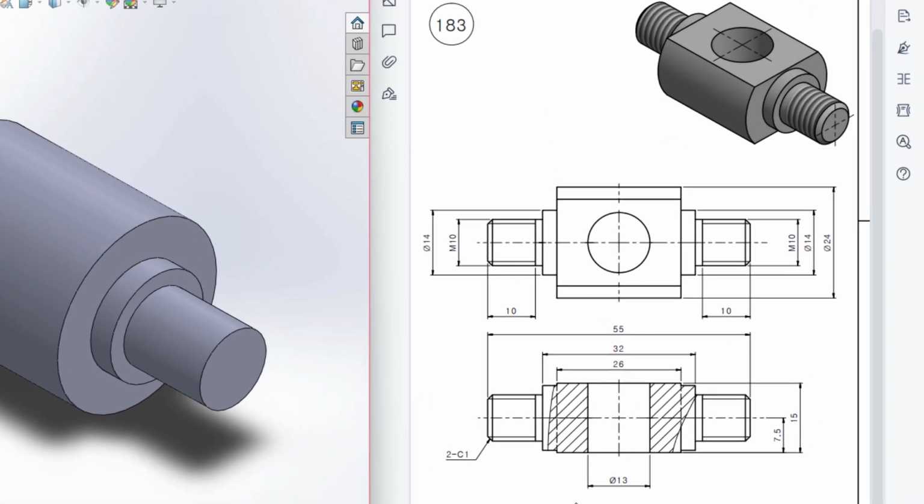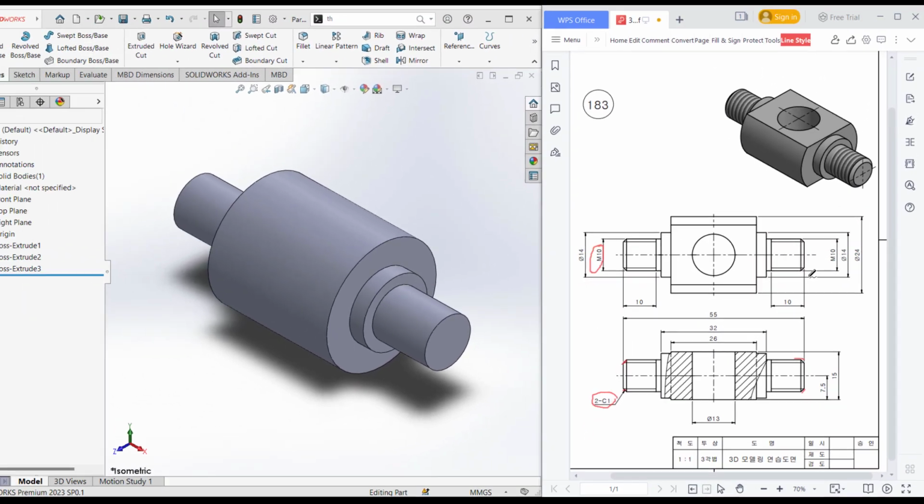Let's go back to our sketch. In our sketch we can see we have an M10 thread, and before that we can see in this corner and this corner and these other two sides also we have a chamfer of C1. Okay, we have a chamfer of C1. As the angle is not given, we are assuming it is a 45-degree angle, and after that we have to do our M10 thread cut. And for doing this M10 thread cut, we can see the thread lies along the 10 unit blind length. Okay, so let's go back to our sketch and draw all of this.